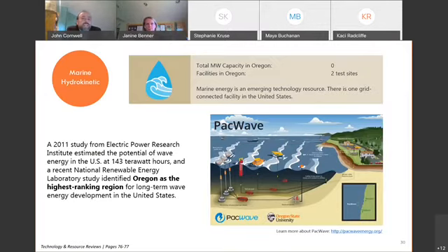So marine hydrokinetic energy technologies capture energy from the movement of water in ocean waves, tides, currents, or also heat energy in ocean waters and convert this energy into electricity. So wave energy technologies, for example, extract energy from surface waves or from pressure fluctuations just below the surface. An example of such a technology is an oscillating water column, which uses the rise and fall of waves to push air through a turbine.